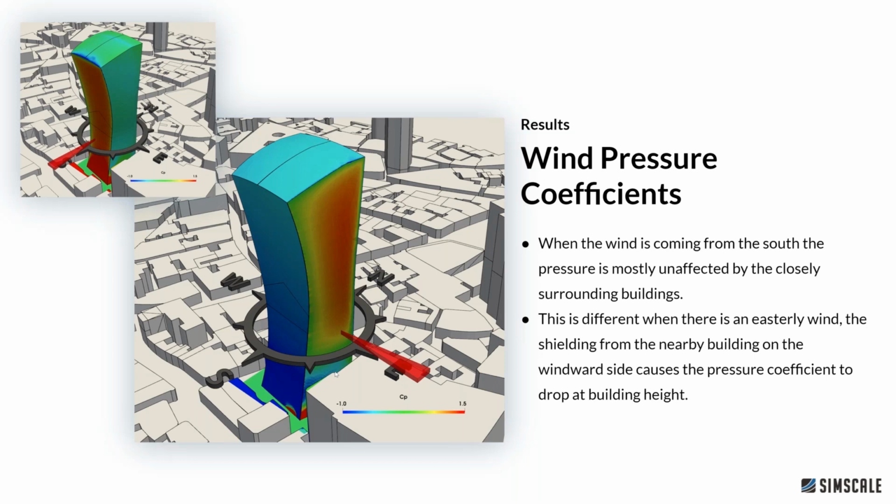We've got very complicated context. We've got tall buildings close. We've got tall buildings far. We've got short buildings surrounding it everywhere. And we couldn't possibly account for all of this when inputting this into a thermal model. But CFD allows you to do that. And for every single direction, it's going to calculate the flows. It's going to calculate the pressure coefficients very accurately for every single direction.